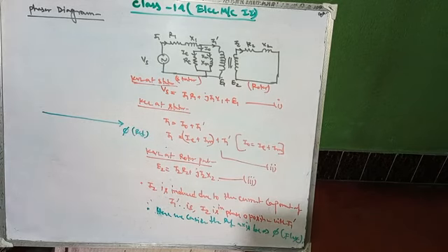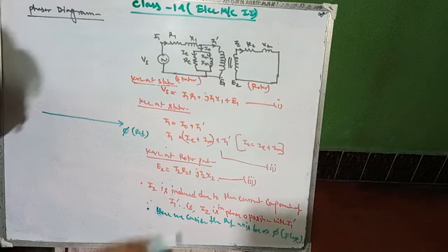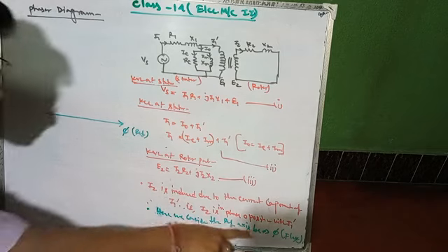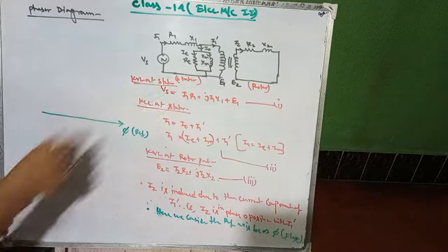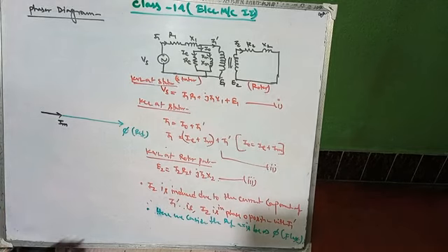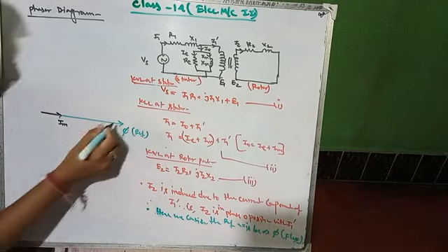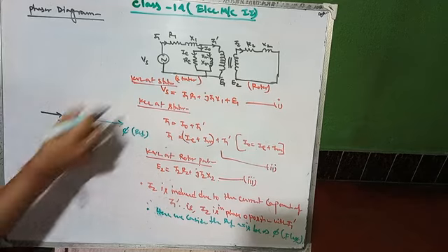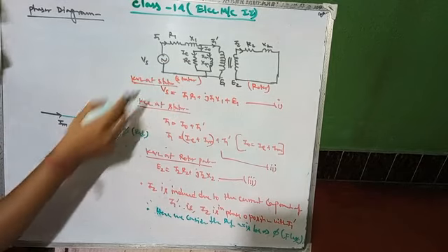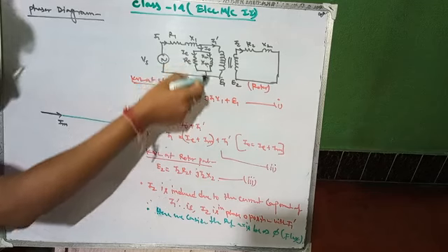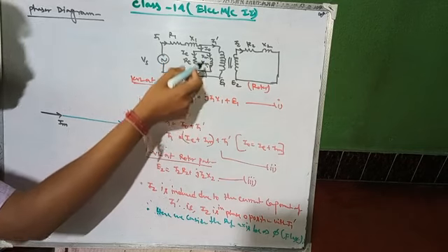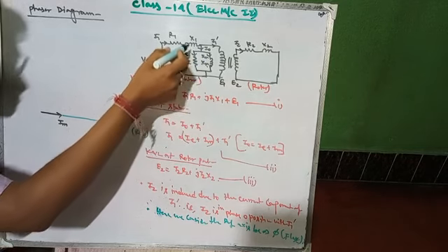Okay, first I have to draw the second equation. Always remember, phi is a magnetic component and Im is a magnetic component, so phi and Im are always in the same phase. Write these comments also: Im and phi are always in the same phase. And as IE is an electrical component and Im is a magnetic component, Im is a reactive component and IE is the resistive component, right?